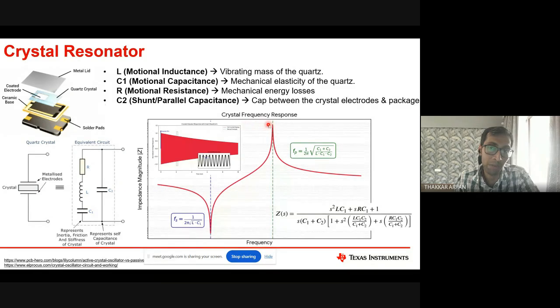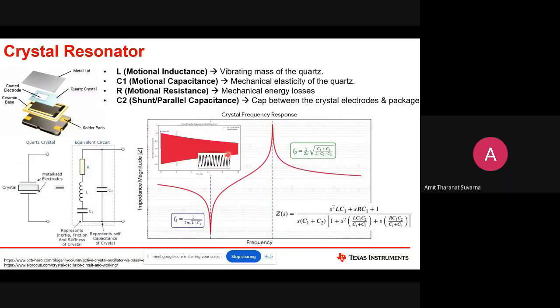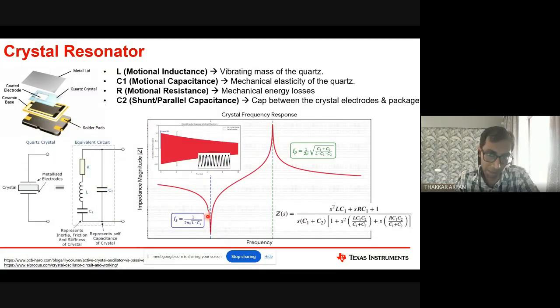At maximum, it will come inside, and this curve will become almost here. You understand? Because C2 plus infinite cap is like infinite cap. Now infinite cap in series with C1 is nothing but C1, right? So it will become like this, a high steep signal. So that's the maximum you can pull it.